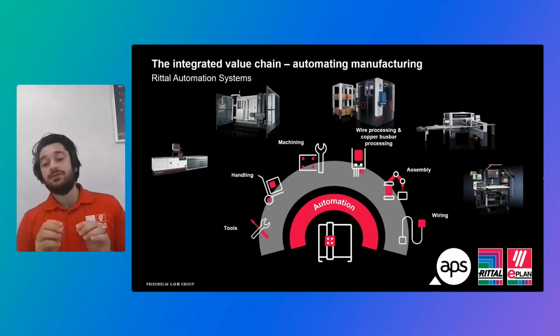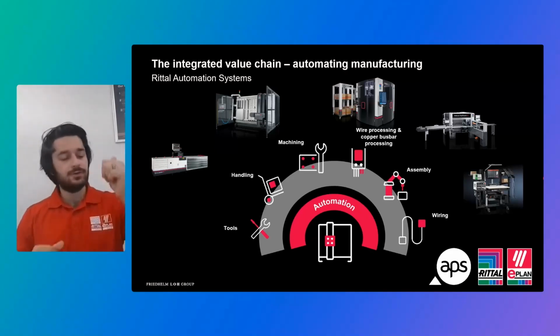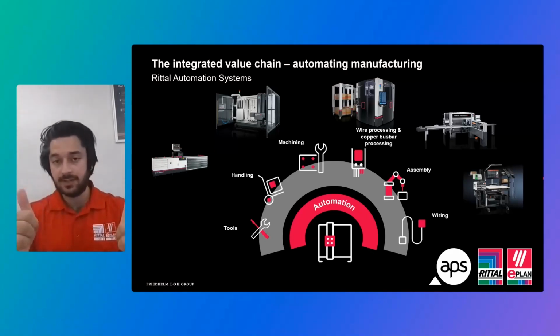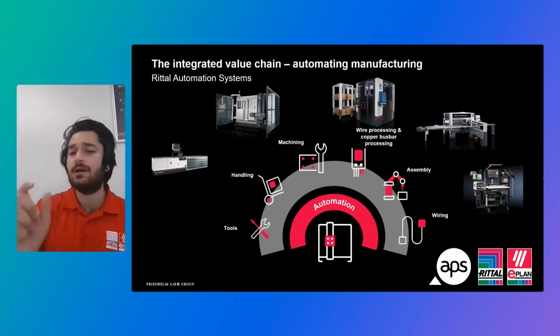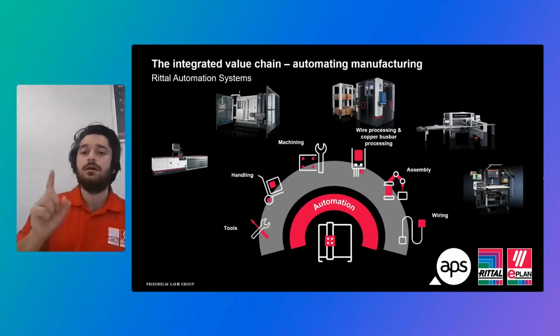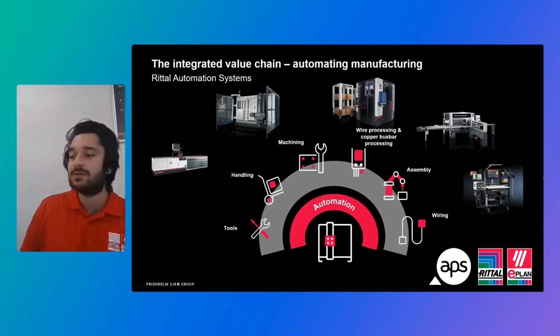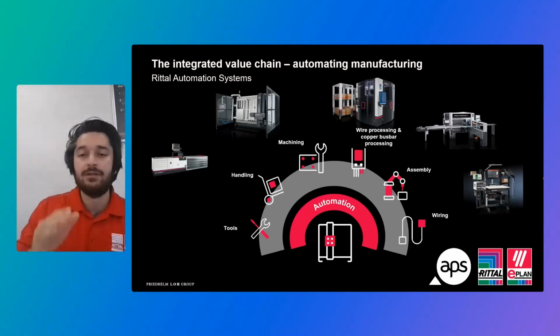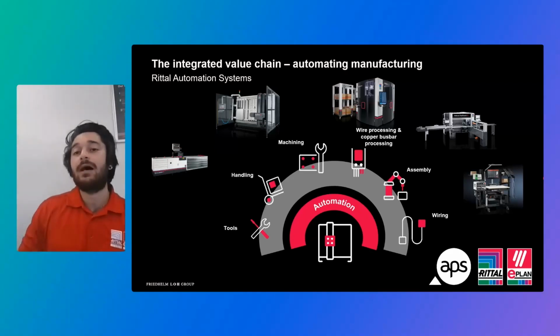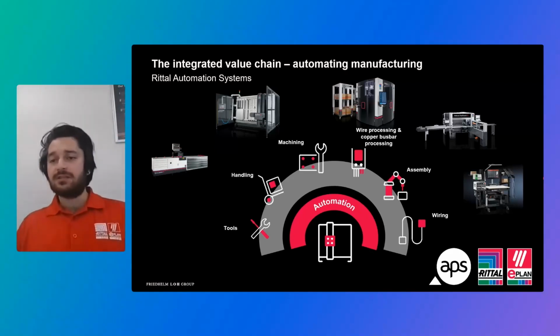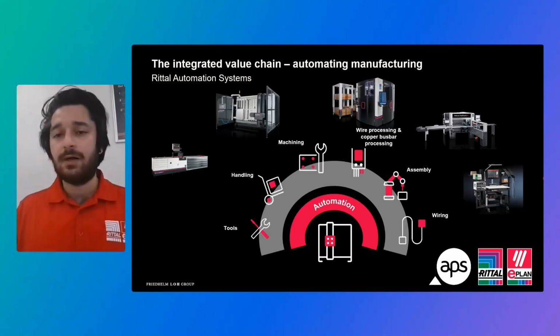Once you have created your engineering drawings, so for instance, you've placed device A, device B, made a connection between them using a specific connection, part number, color, cross-section diameter, this wire terminal will just start cutting, bundling everything for you automatically. Something that might take a person 1, 2, 3, 7, 10, 20 hours could be done in a matter of minutes. We also have the whole flex punch machine as well, whole cut flex punch.